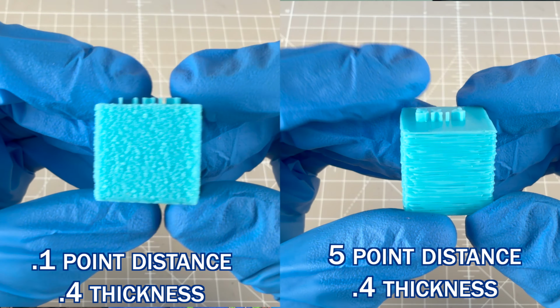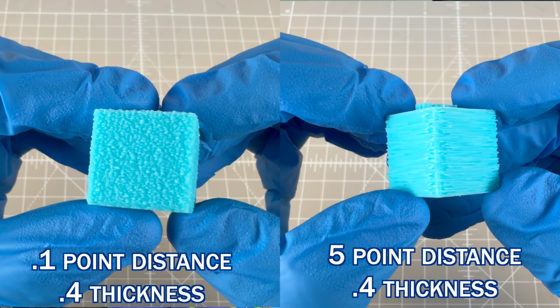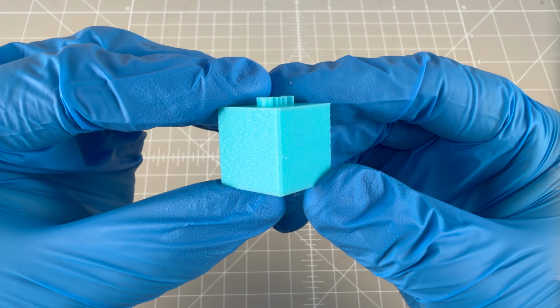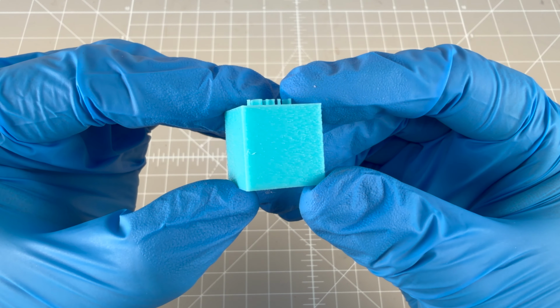We can do a similar comparison where we keep thickness at a steady 0.4 and see that as the point distance increases, the peaks and valleys stay roughly the same, but the distance between those peaks gets larger. I also mentioned earlier that fuzzy skin can hide layer lines, but you have to get the settings right. In my opinion, the layer lines were hidden best with a point distance of 0.5 and a thickness of 0.1,